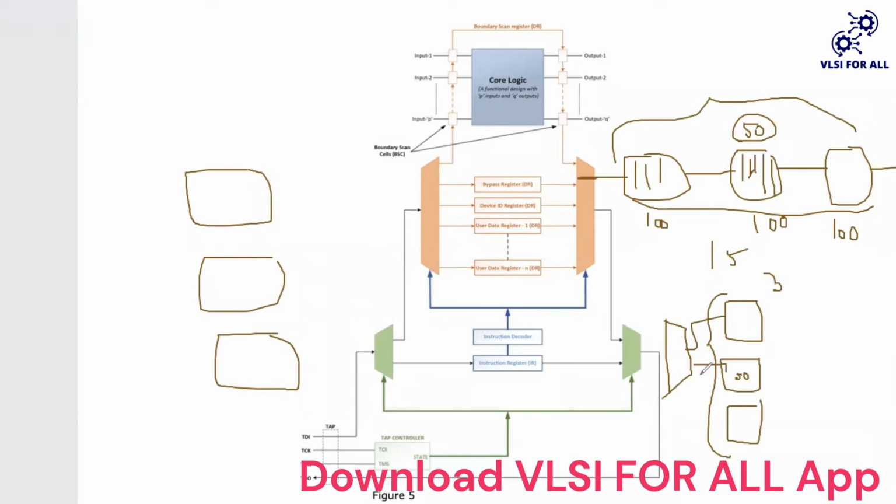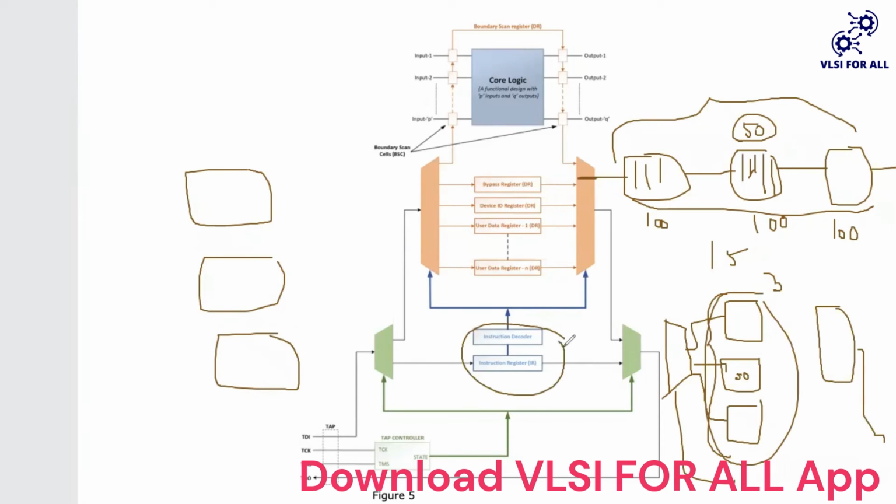Based upon the select lines, one out of these will be getting selected. And similarly, one out of these will be getting to the output. So this logic is that selection process. Basically, out of these 3, which one do I need to select? That is based upon this instruction register, which will be selecting out of these registers, and similarly selecting out to the TDO. Basically, this one, if you see, is going to the TDO.